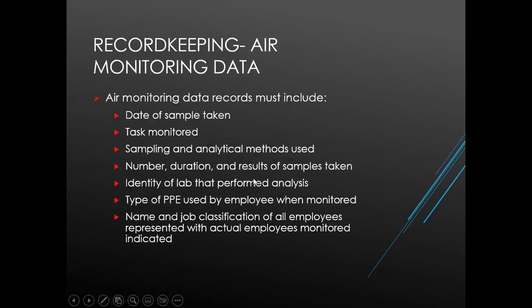Record keeping for the air monitoring data should address the date of measurement for each sample taken, the task monitored, sampling and analytical methods used, number, duration, and results of samples taken, identity of the laboratory that performed the analysis, type of personal protective equipment such as respirators worn by the employees monitored, and name and job classification of all employees represented by the monitoring, indicating which employees were actually monitored.